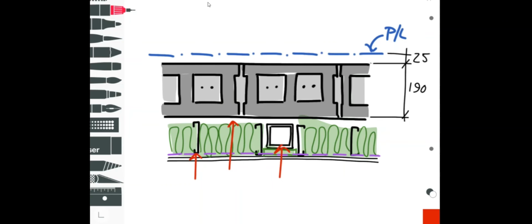So the steel stud wall just gets built, and you would insulate in the cavity spaces of the steel stud wall. If it was minus 20 out here or something like that, then this surface right here on the concrete block would be cold, so you wouldn't want some warm moisture-laden air getting to that surface. So I've added in a vapor barrier as well. That would be the cheap and nasty, normal way, or a way it's been done in the past.